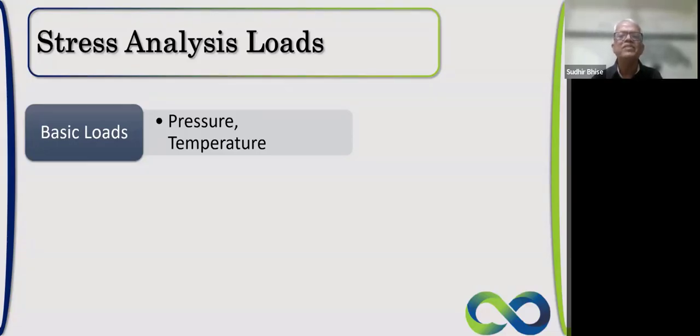Only very few lines are expected to be at pressures beyond 75 bar. Only in such cases will there be some effect of pressure on the flexibility of the piping. Otherwise, pressure does not play an important role in the analysis.